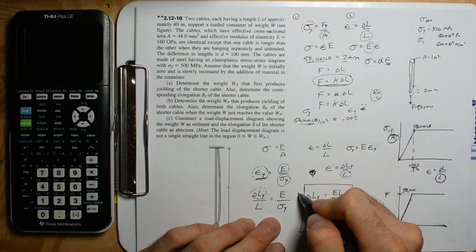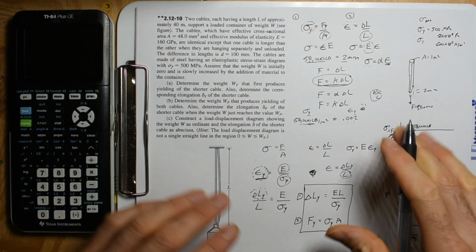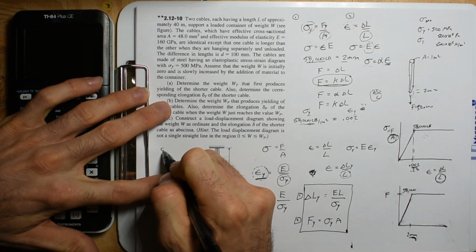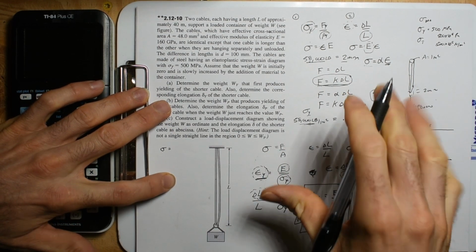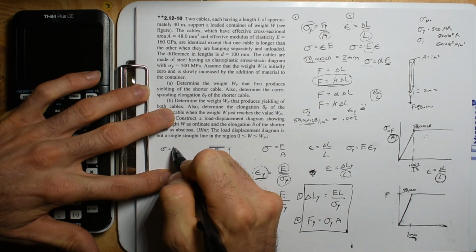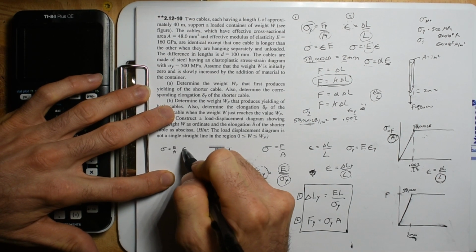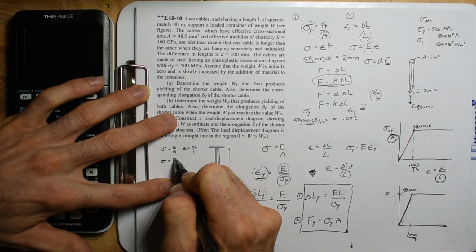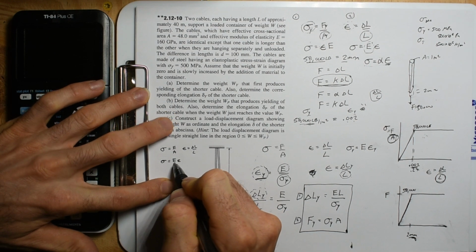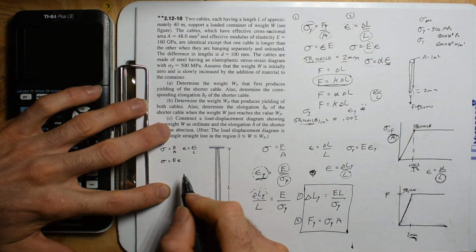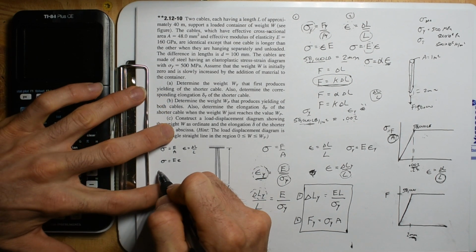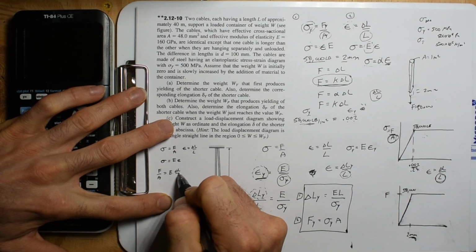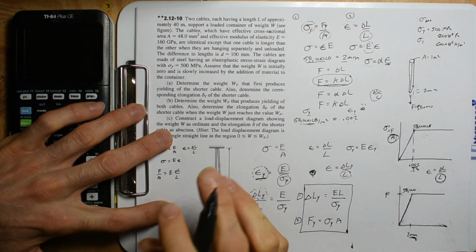Even though I made that hella complicated, at the end of the day, if you're doing a material mechanics problem for the first time, you want to get all these equations on paper. F over A. You want to get strain is change in length over length. Then you want to get the ratio between them, and I guess I will start doing this E this way, because this is your constant. So then you can throw these in. F over A is equal to the constant, and then throw this in for E, change in length over length, and then you can rearrange to whatever you want.